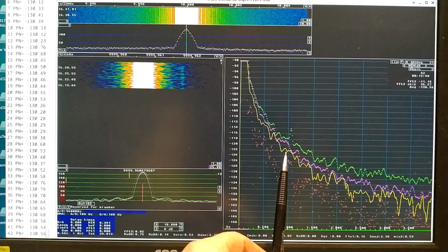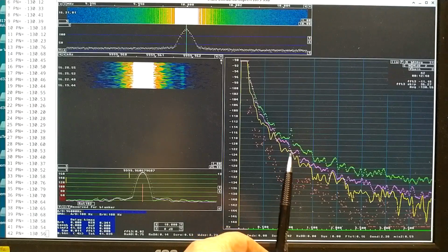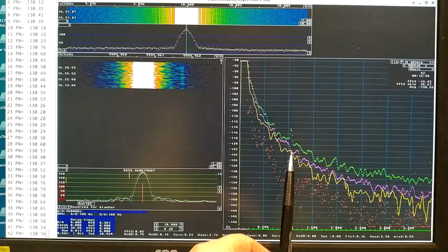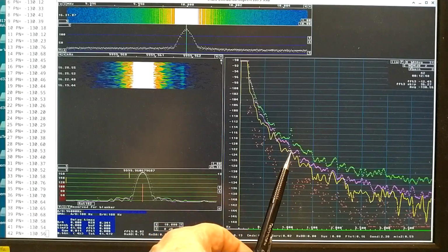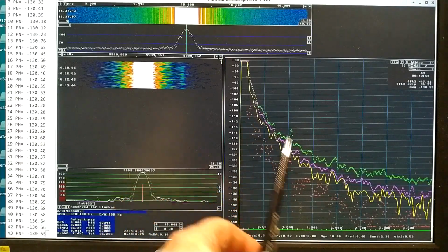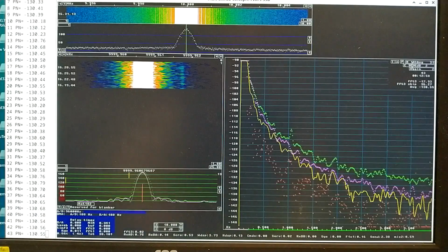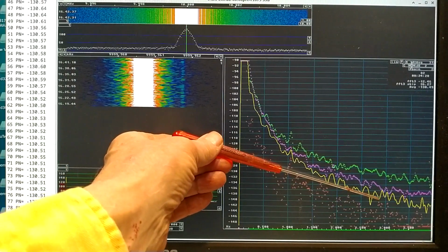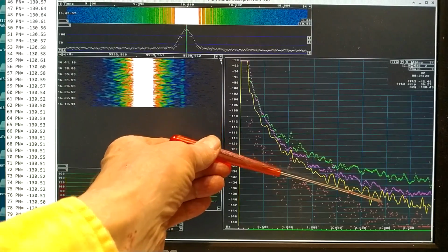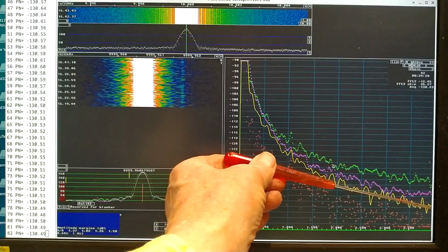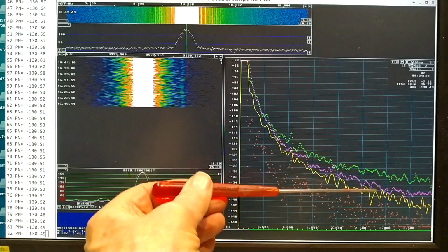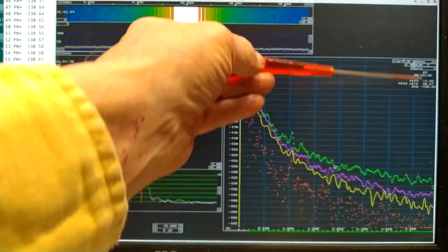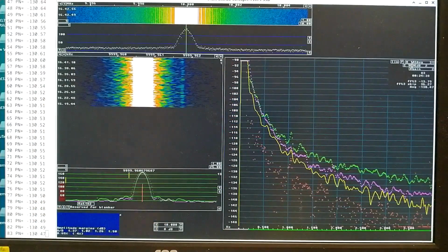If I wait long enough, I can see on the correlated curve whether there is something that is also present in channel 2. Anyway, it is weak enough to not affect the average noise over this entire range. Now, most of the data points are within plus minus 2 decibels, 2.5 here, and also here, but very few. And this is 24 minutes with 82 averages.